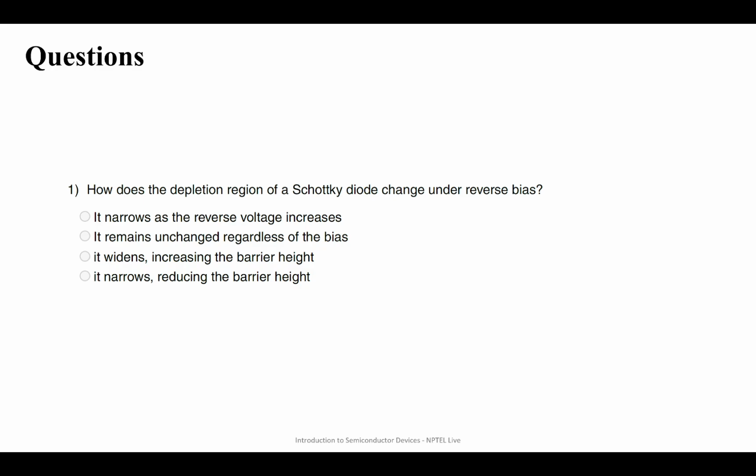Ballistic transport is different, and 2DEG is different. So 2DEG is causing your high mobility, and ballistic transport is caused due to a very thin channel region. Basically your semiconductor channel, which is the length between your source and drain of the semiconductor, is very thin. That is smaller than your collision length of electrons.